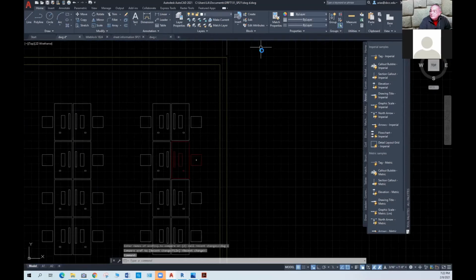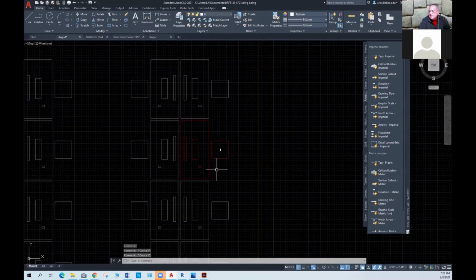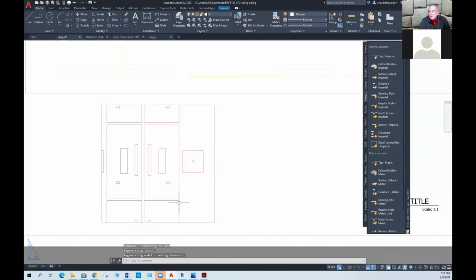Save the drawing, get back to, I'm just using Control Tab, or I could go to Drawing D, reload. And one of the things that we need to make sure is that we see the change we did. See, that is in that particular layer. Now what I'm going to do is go to A2, and I am going to turn off in this viewport all the other layers.